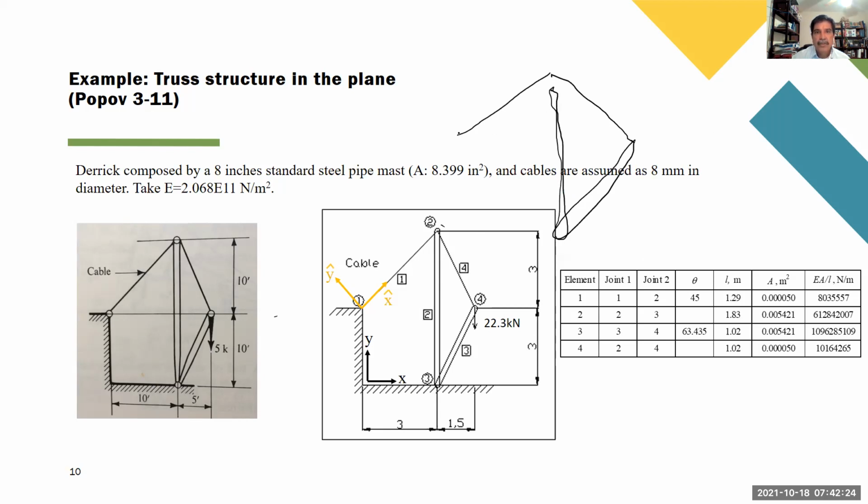Okay, so you draw this point, this point, this point, and this point. And there are some cases when the program understands or doesn't understand that this end is the same as that joint, and leaves these 2 points not connected. So when you apply a force here, this element will develop no stress.